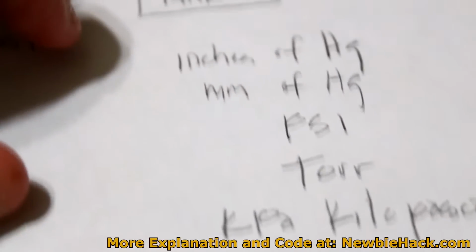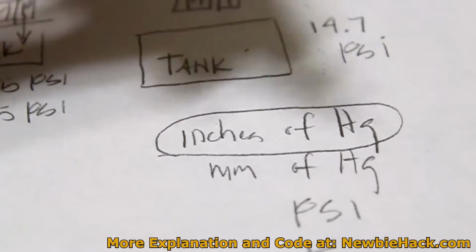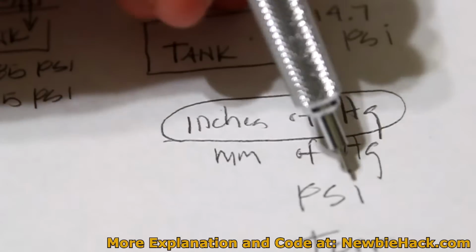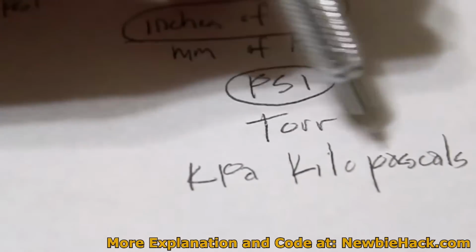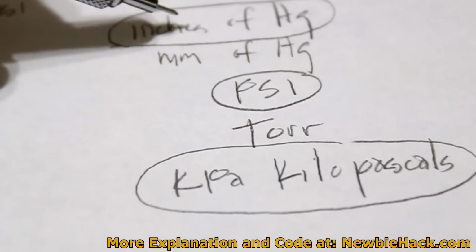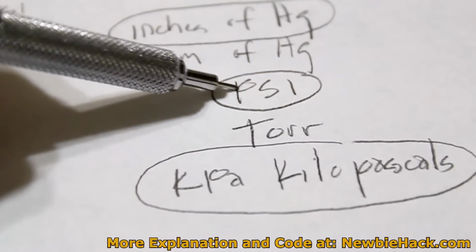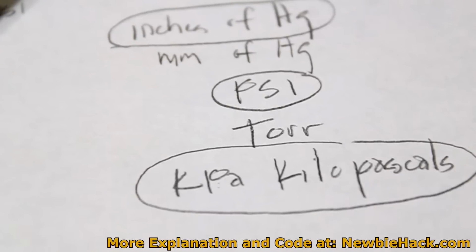In this video, I'm generally going to be talking in inches of mercury, and every now and then I may give the equivalence of what the psi is and maybe the kPa, because some of the sensors use the kPa, some sensors use inches of mercury and psi. Most sensors you'll find use psi or kPa, kilopascals.